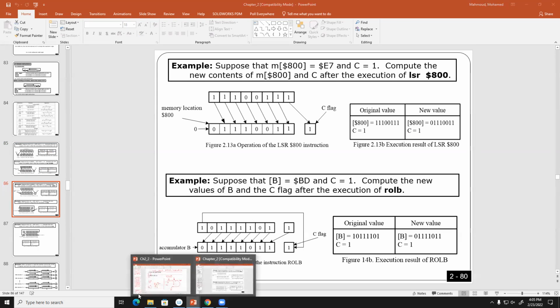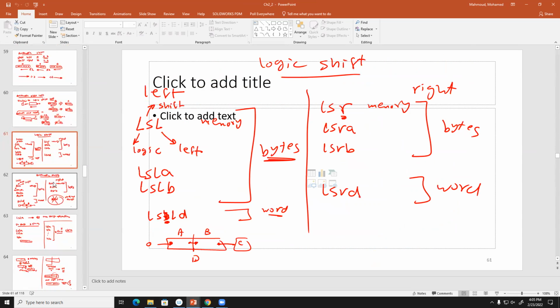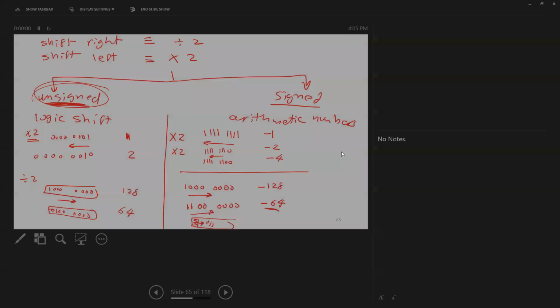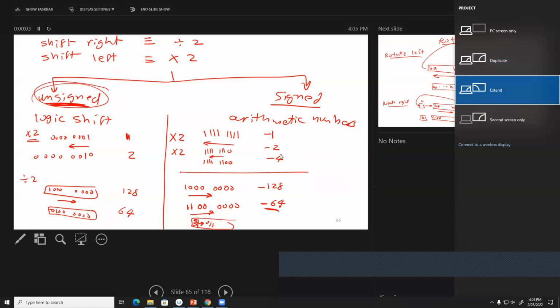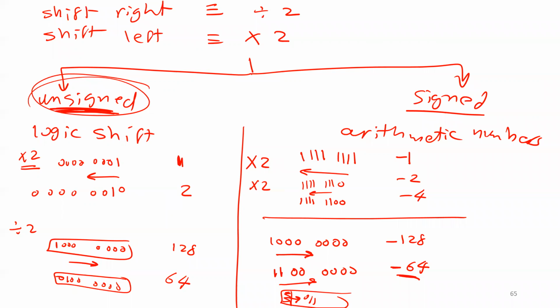Okay, great. So what I want to explain here, guys, before I start the rotate instructions, is I told you last time we can use shift to multiply by 2 or divide by 2, right? Some people, especially the people who are implementing crypto systems, because in crypto systems we usually have very large numbers, if you want to divide by 2 many times, shift can divide by 2 or multiply by 2 much more efficiently than using the multiplication and division instructions I taught before, because shift is efficient. Once you shift, you just divide by 2 or multiply by 2.